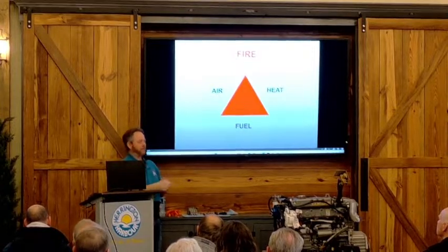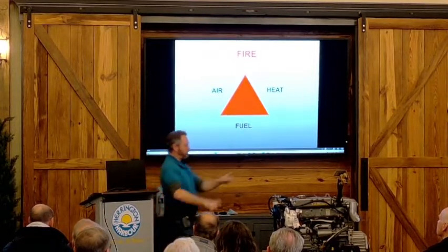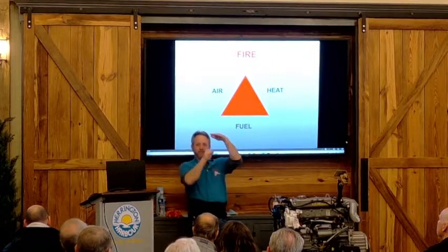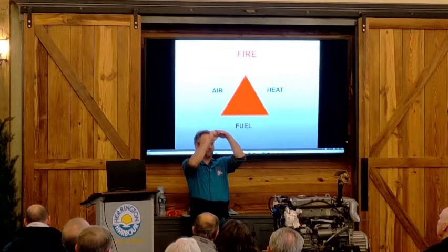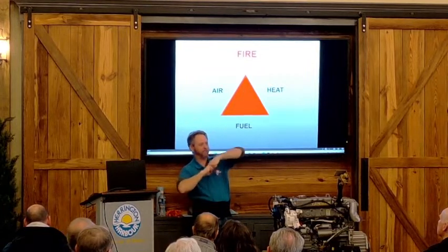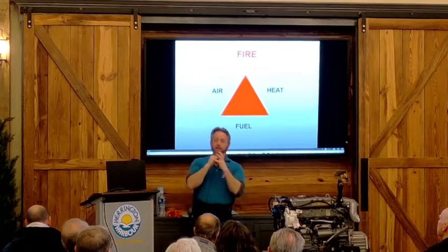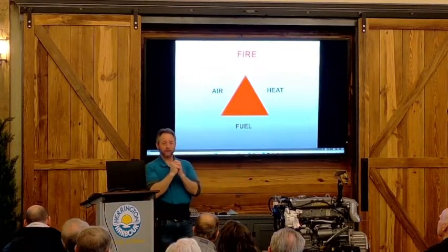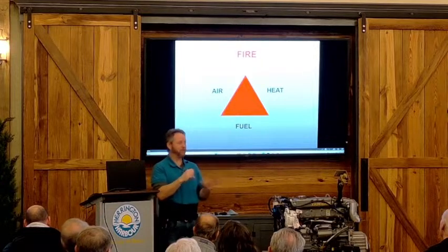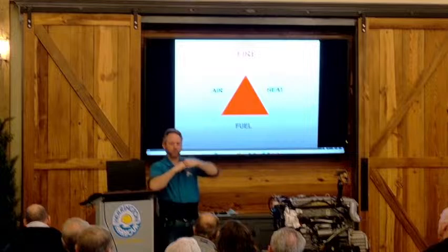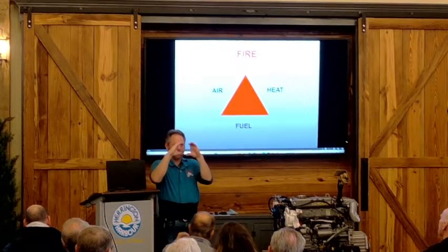So what happens when you hit this engine with starting fluid is that the starting fluid ignites before the piston is high enough in the cylinder to come back down. So you have opposing forces, and a lot of times it's the piston that loses. Most of our pistons are made out of aluminum, and when you have opposing forces, that piston compresses down a little bit.